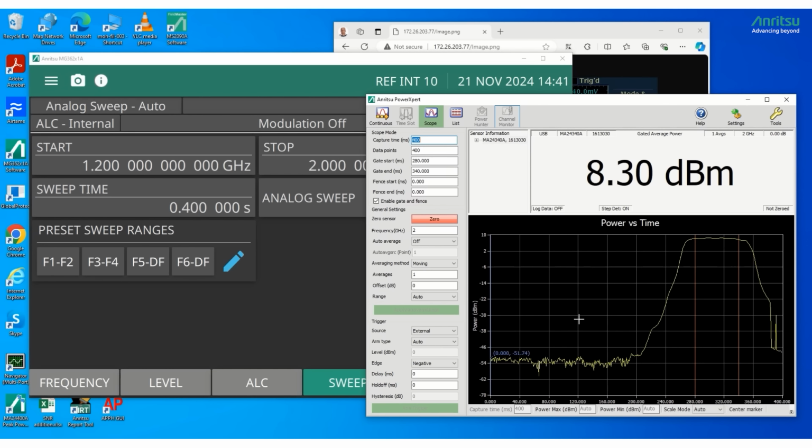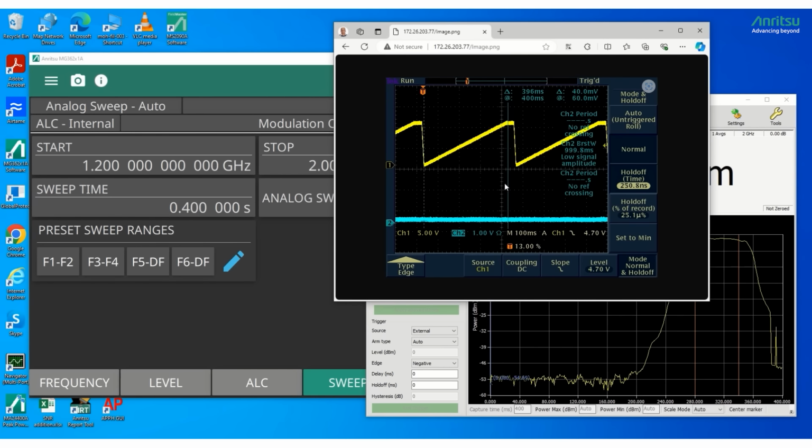Let's look at what is happening here at the higher end of the stop band, and you see a small spike here. It's showing you a very concentrated RF output power at this point. If you recall my scope snapshot, I talked about a brief horizontal period in the sweep signal, which is where the RF output rests a bit before starting its retrace.